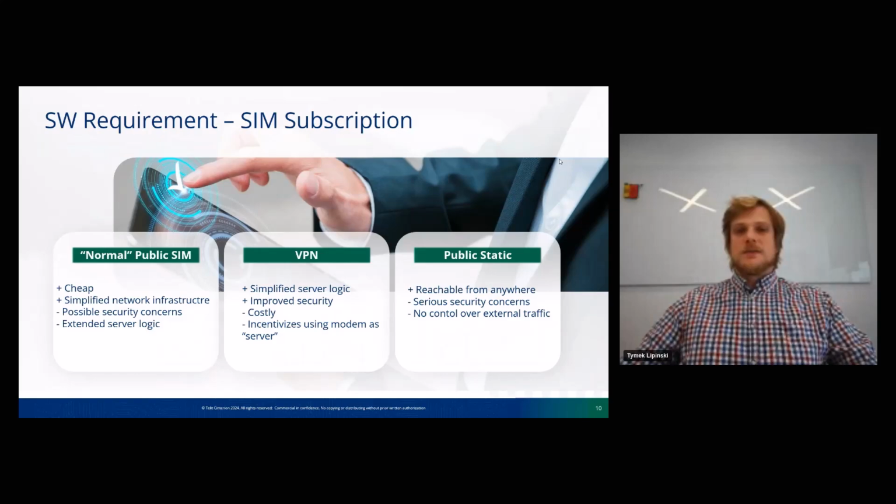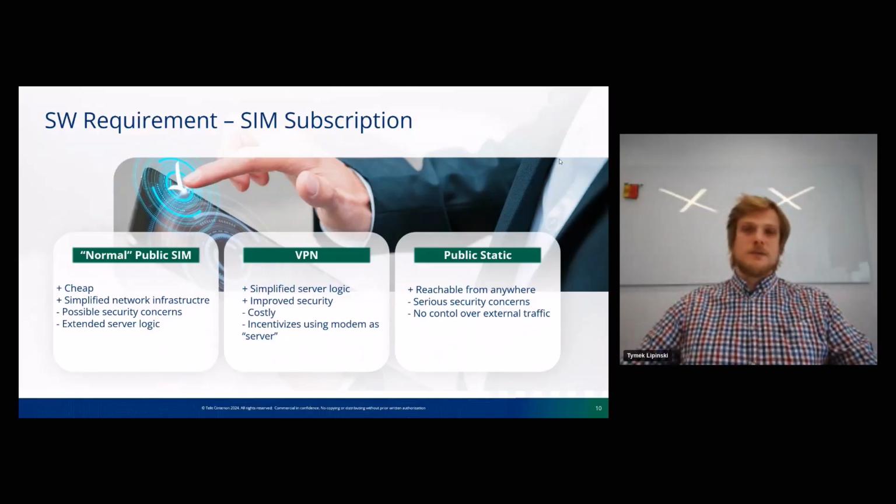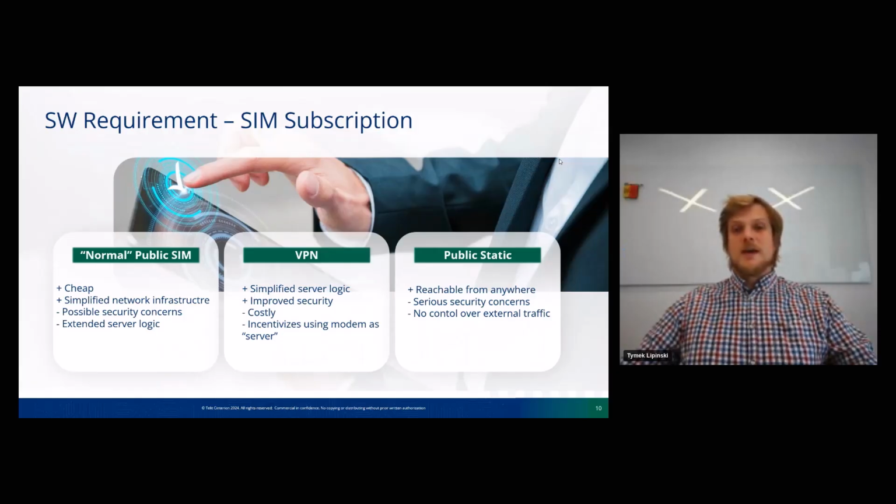VPN, on the other hand, simplifies server logic. It has very improved security because it's a virtual private network. No external actor can get into this network. But operators require extra payment for the VPN option, so it's costly. And unfortunately, as VPN usually means that a certain SIM card has a static assigned IP, it incentivizes using the modem as a server, which is not the greatest idea, which we will explain later.